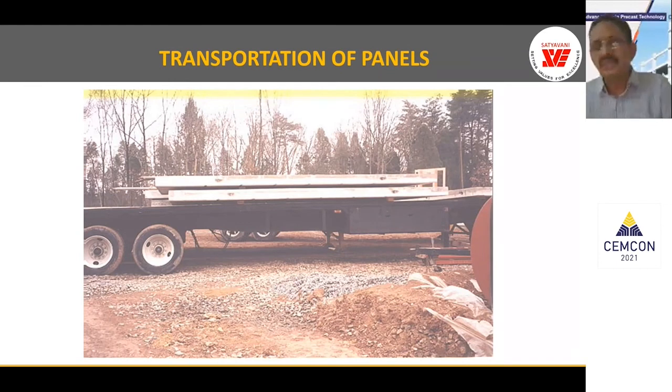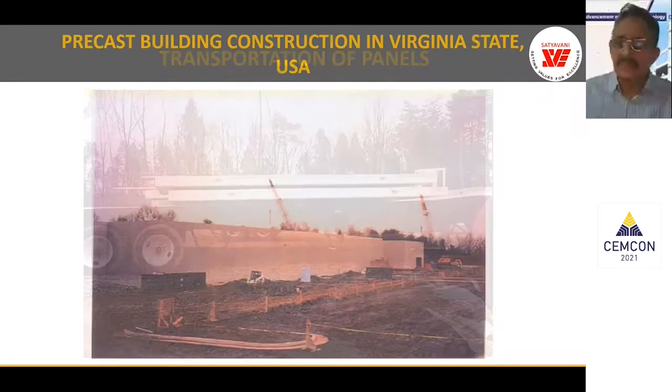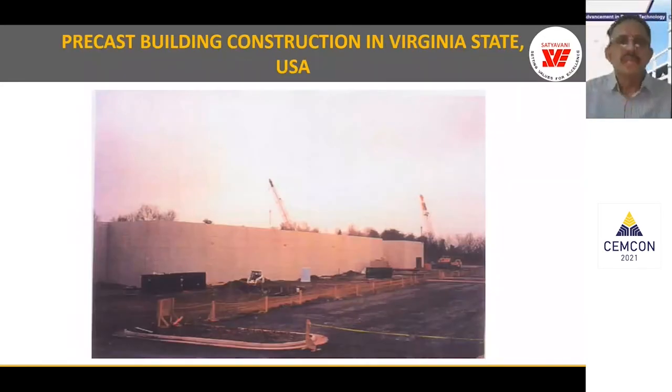Why I'm showing all this is that when we consider precast, we also have to consider the accessibility to the site and the clearance of the site, without power lines or distribution lines and all. We have to keep in mind how a trailer can reach the site and how a crane can lift and erect these panels. Maneuverability of these large panels. Here you can see how much open space is available. So it is also important to have enough open space around the building.